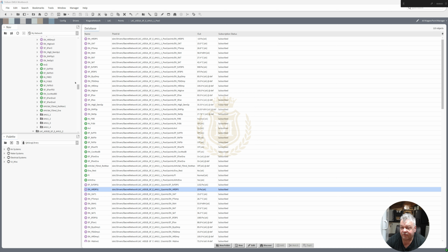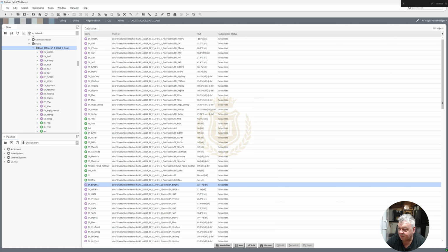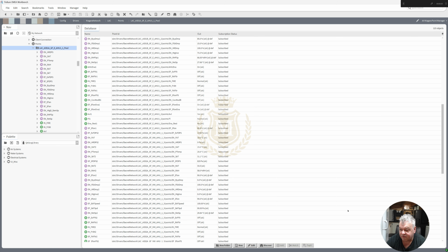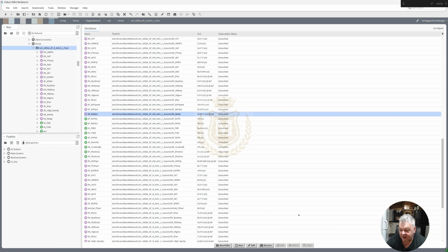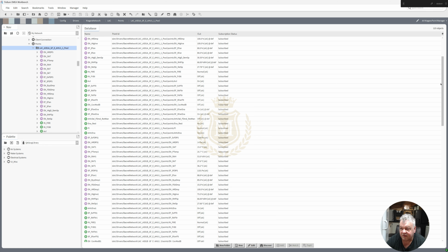So I've brought some points across to the supervisor from the station, and this particular station is basically saying it's AHU 1 up at the top here, but it's not. Ground floor east AHU 1 pool. But looking at the points, I've got AHU 1 in here, and then I've got AHU 2, and then scrolling down I've got AHU 3, and further down I've got AHU 4. So I'm putting these in their own folders on the supervisor.